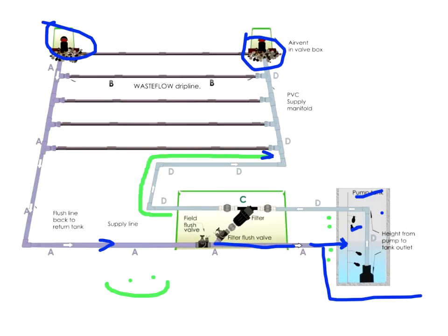Then I'd suggest putting another settling basin in here, and have the water come up into it and settle, and as it overflows, let it overflow gently into the pump tank.